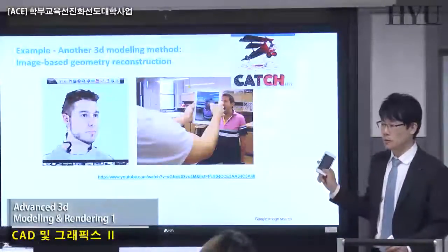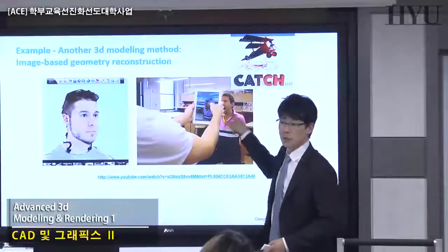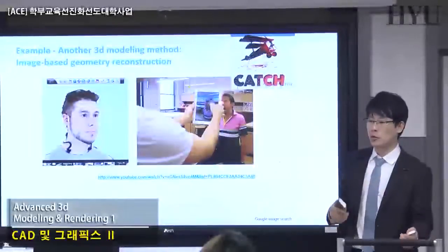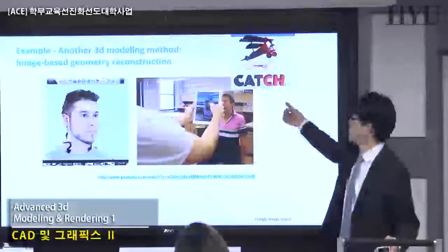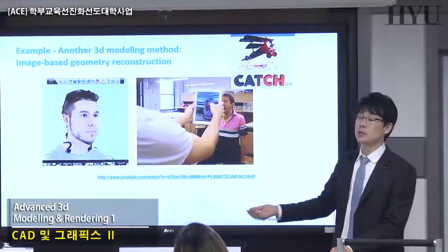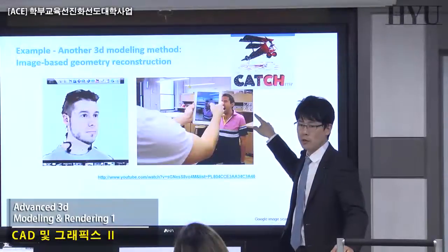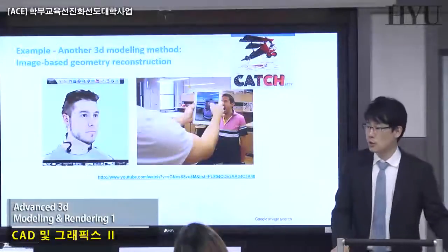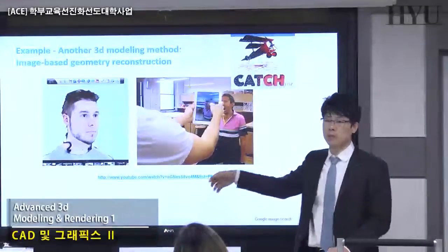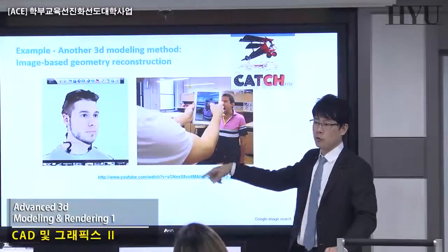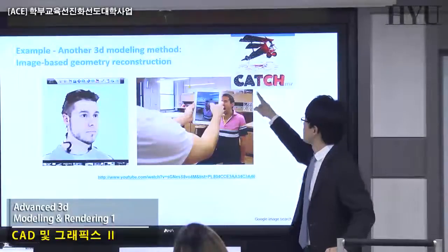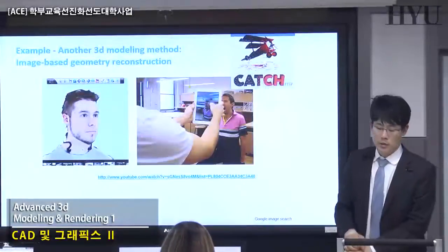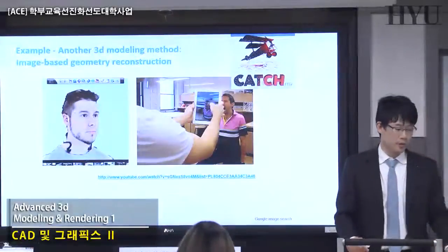You can use a smartphone to take a series of pictures, not the face of your friend, but this kind of complicated shape object. You can take a series of pictures, load them into the cloud server of Autodesk, and open it using your PC version of 123D Catch. Then you can generate an editable poly 3D mesh of this structure, okay? Or your friend's face like this one. But this chair, or the surface of this interior, this room, can be captured easily by clicking your snapshot button. Anyway, the PC version will generate this kind of mesh, editable poly, directly importable into 3D Max, okay? Please try that, and I'm going to show you a demonstration later, okay?